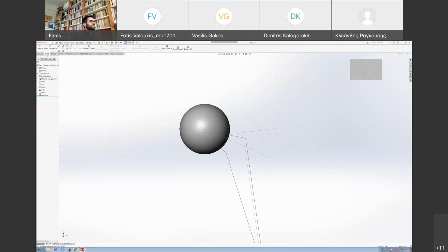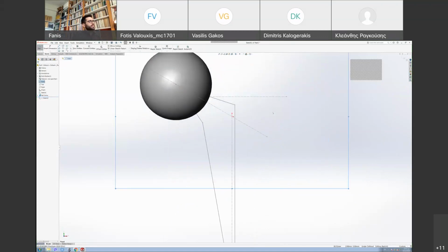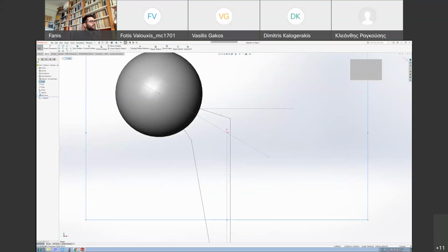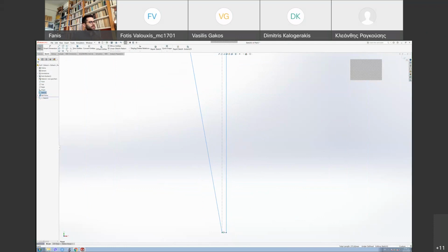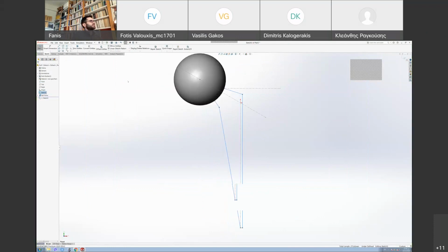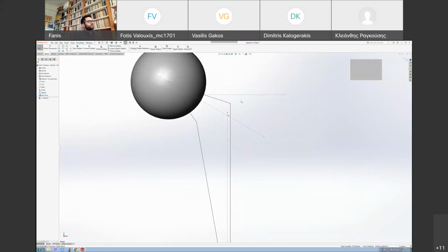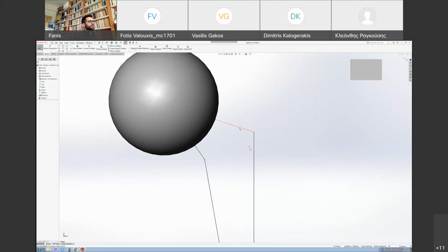And now again in sketch, we're gonna make the handle, let's say, or the rest of the bone. Again, go to the front plane, sketch. Let's bring it vertically. And now, in order not to design all these things again, you can just choose these lines. Okay. You can say convert entities, so it brings it to your sketch. So even if I hide the sketch, for example, now I still have these lines in my sketch, which is pretty helpful. And now I will convert these lines for construction, and I will explain why.